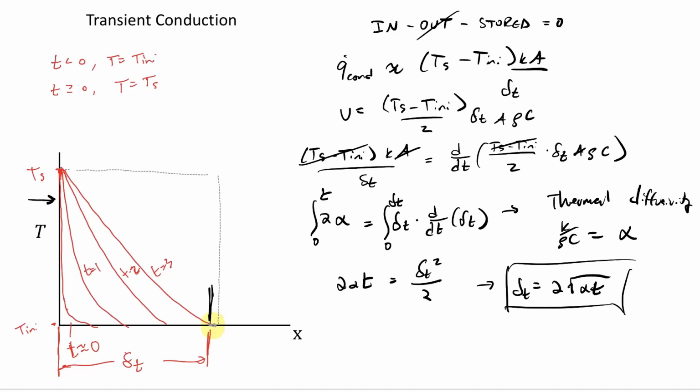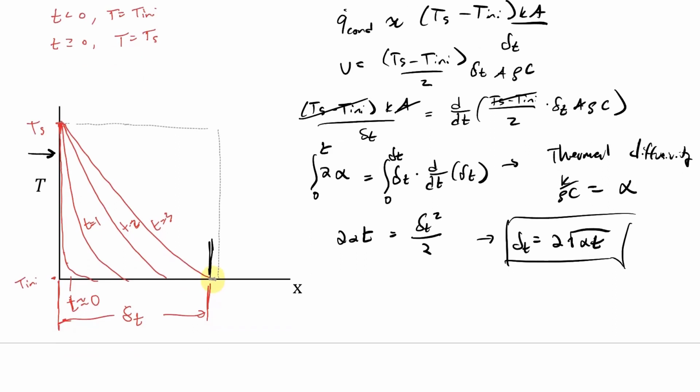So this equation, you can use quite a bit. It's one of the time constants, one of the things you can really use to characterize a problem. In fact, we can rewrite this as a time constant. We're going to solve for T, and we'll call this tau diff, or diffusive time constant. Tau diff is equal to L squared over 4 alpha.